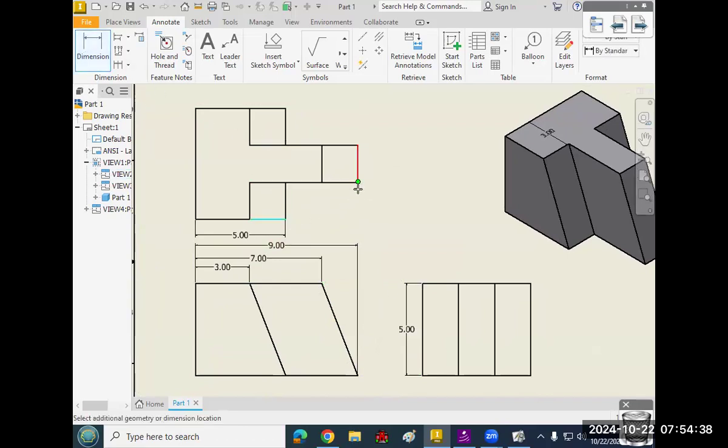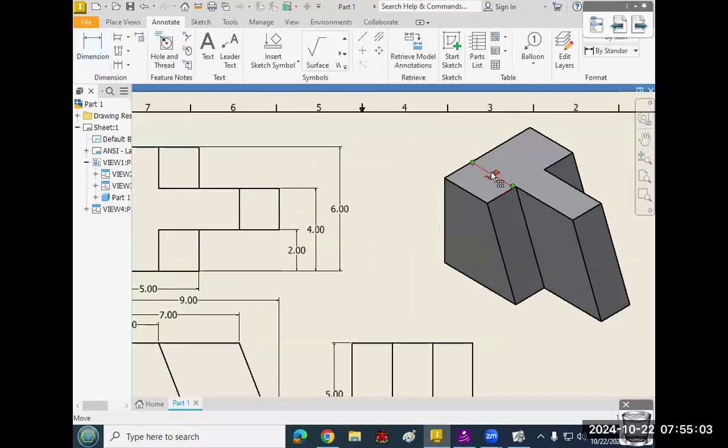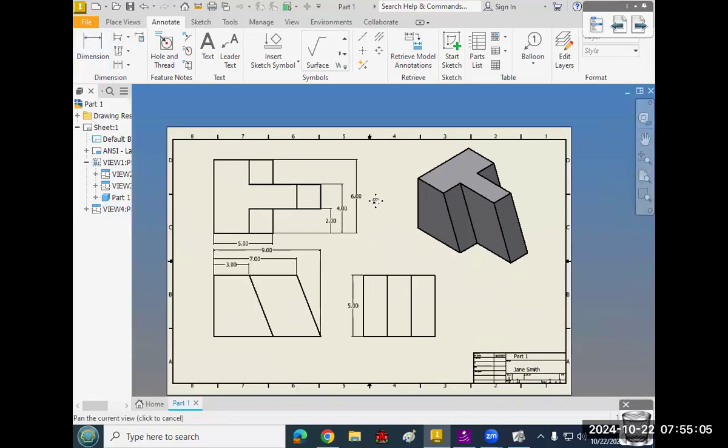And depth, front to back. First thing that happens is this. That's fine. And it goes to a contour. I'm not crazy about long extension lines, but it's still better than an interior line. Okay, and so that's the first thing that happens. And that same process or same options apply to the other two depth dimensions. And I'll get rid of this because we're not dimensioning to our isometric views.